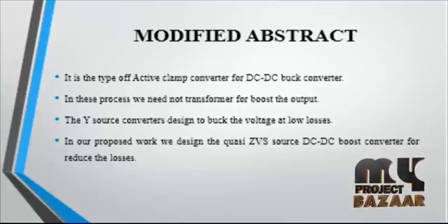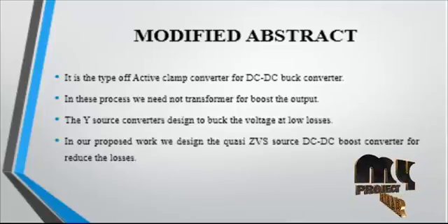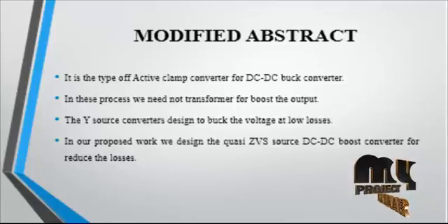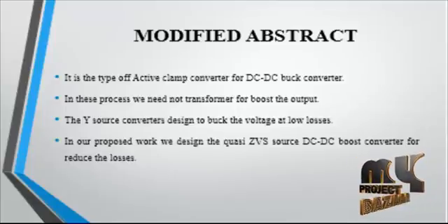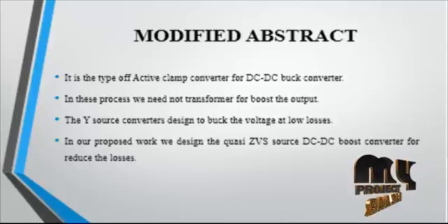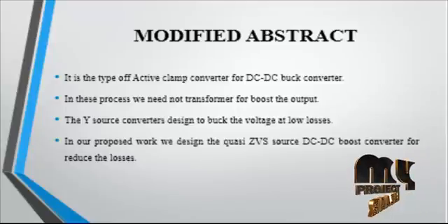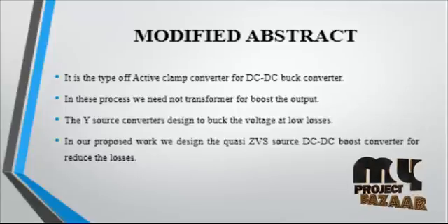The steady state stability analysis is presented on account of the losses and damping inherent in active clamp converters. It appears that the stability region in the current controlled active clamp converters gets extended for duty ratios a little greater than 0.5, unlike in conventional hard switching converters.